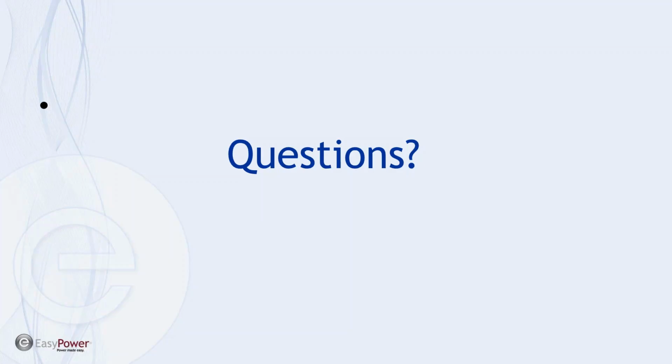Again, I'm trying to interpret these questions. So I don't encourage that we prescriptively put the PPE on a label, right? The label should be the arc flash hazard information. The PPE is specified and procured by the employer through the information and electrical safety program. Again, that's my opinion. That's my interpretation of 70E and Z462. Ultimately, an employer can do whatever they want with respect to how they present the arc flash and shock data on an equipment label, right?